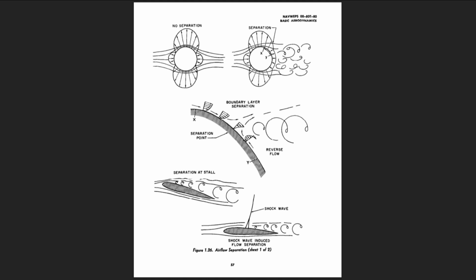An airfoil at some high angle of attack creates a pressure gradient on the upper surface too severe to allow the boundary layer to adhere to the surface. When the airflow does not adhere to the surface near the leading edge, the high suction pressures are lost and stall occurs. When the shock wave forms on the upper surface of a wing at high subsonic speeds, the increase of static pressure through the shock wave creates a very strong obstacle for the boundary layer. If the shock wave is sufficiently strong, separation will follow and compressibility buffet will result from the turbulent wake or separated flow.